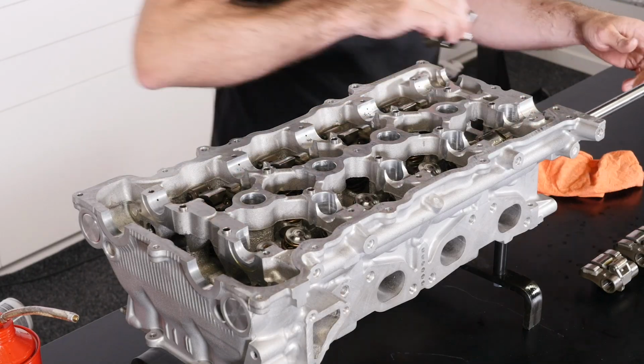Before we jump onto the ignition retard though, I just want to add a little caveat here for safety. Just understand that an ignition cut limiter can be very, very dangerous on some engines, particularly engines with a fragile valve train. The SR20 is a really good example where they've got a very heavy lifter, a rocker I should say, in the cylinder head. The ignition cut can provide large pulses in the exhaust manifold, which can actually bounce the exhaust valves back off their seat, and this can end up potentially, in the SR20 case, popping the rockers off and causing all sorts of damage.